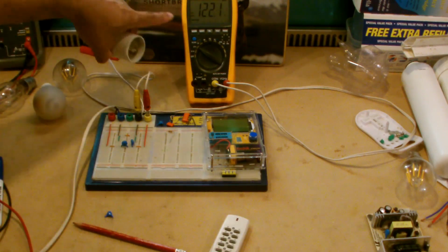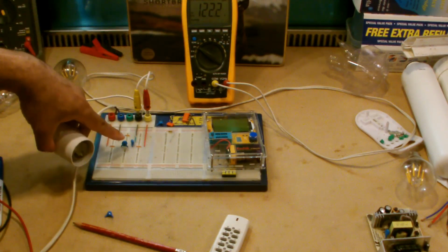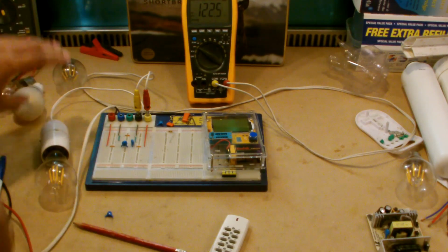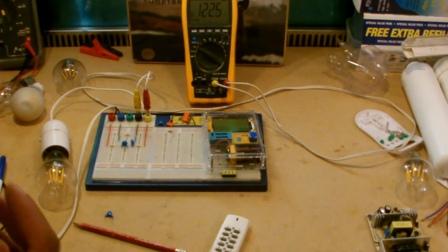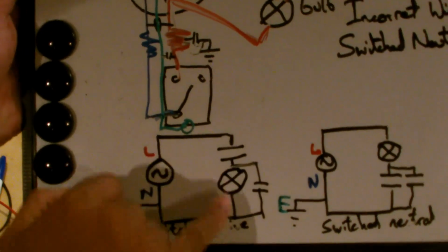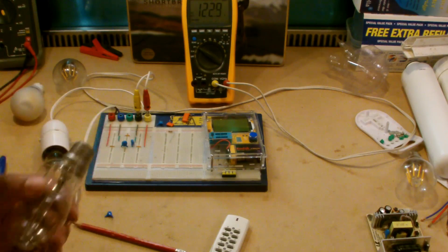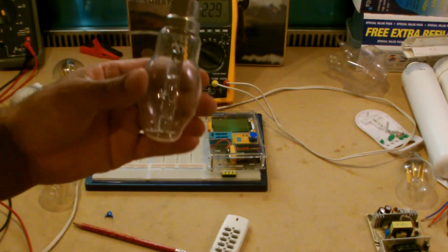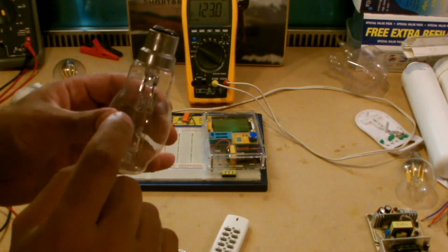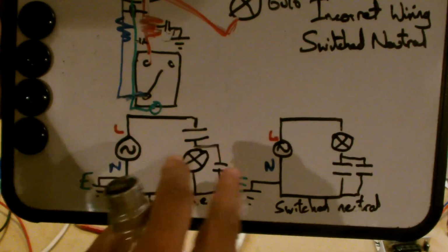You'll notice that if I take this out and you look at the voltage here, you'll see it's 120. So it's actually split the voltage here. And as you can see, the environmental effect of having that cap, and that is the next of the 5 solutions, number 3, which is you can shunt across that bulb. So the easiest way to do that is, if say for instance you have GU4s, the tiny little LEDs, is to put one of the tiny little GU4 halogens with the rest of them, and that one little halogen will be across this and it will consume that power.